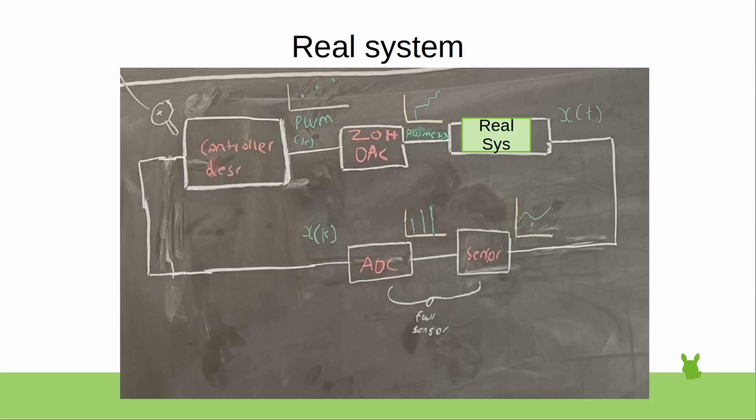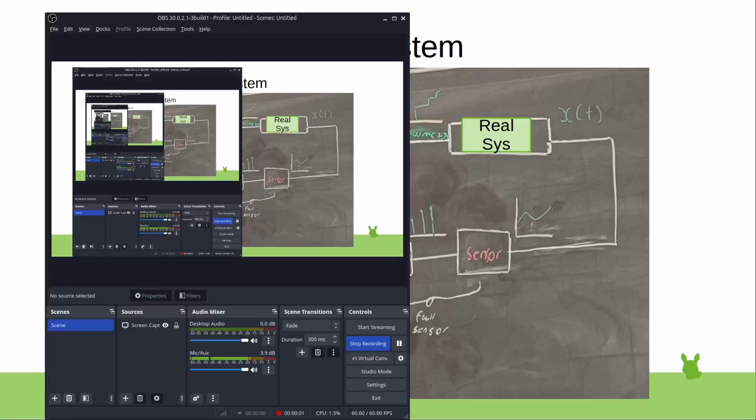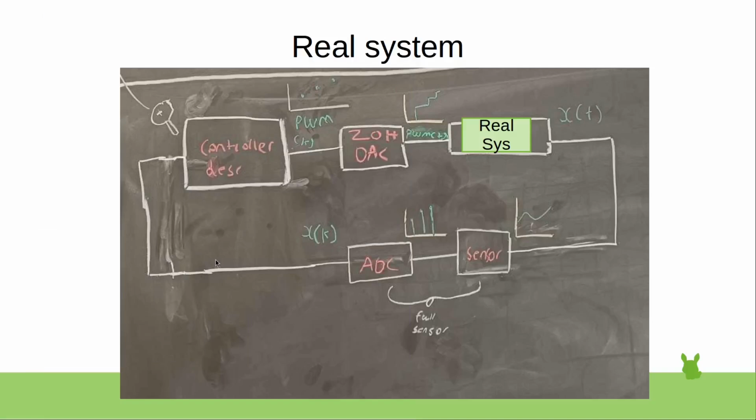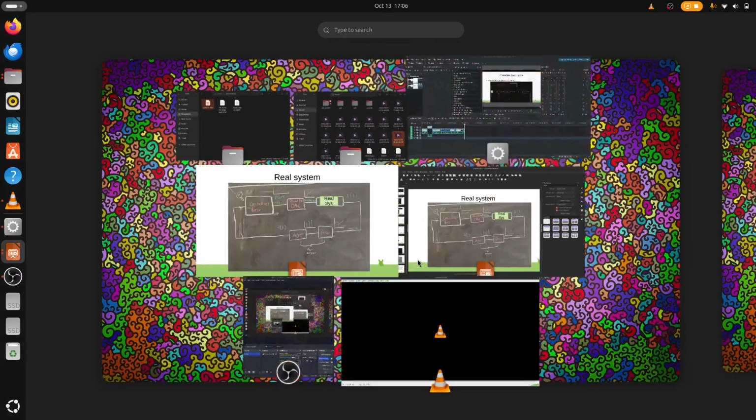What the controller will actually take in is its own limiting discretization. So I want to pinpoint that, in my experience, the limiting discretization usually comes from the controller. But if it comes from the sensor, that's also fine. It's just what discretization your controller will use, and that's what you will have to look at when you're doing the Z transform, when you want to see the discrete dynamics.